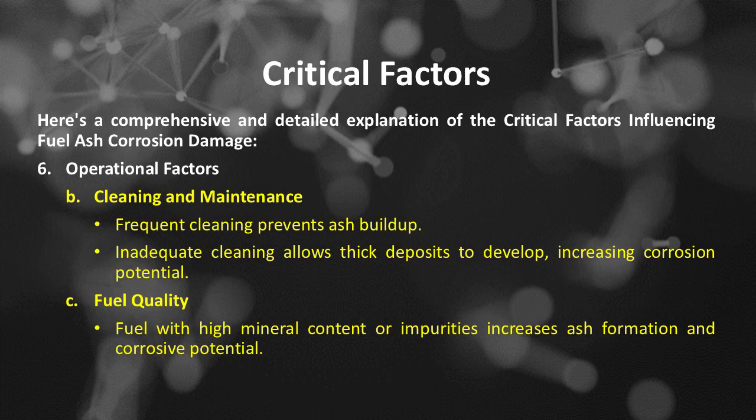Number B. Cleaning and maintenance. Frequent cleaning prevents ash buildup. Inadequate cleaning allows thick deposits to develop, increasing corrosion potential. Number C. Fuel quality. Fuel with high mineral content or impurities increases ash formation and corrosive potential.